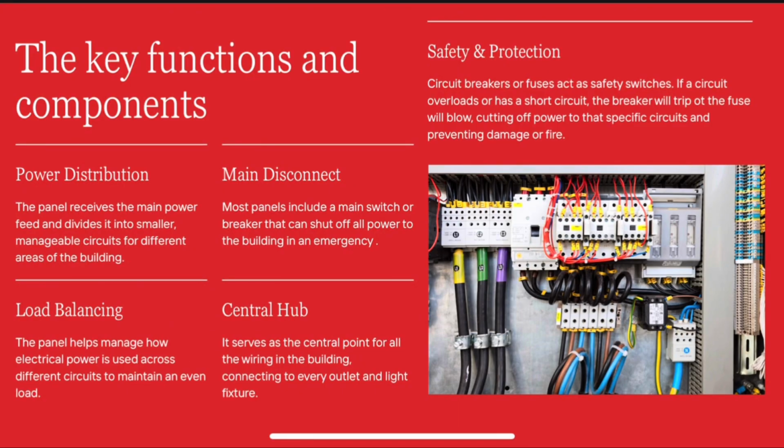Lastly, there is safety and protection. A circuit breaker or fuses act as safety switches. If a circuit overloads or has a short circuit, the breaker will trip or the fuse will blow, cutting off power to that specific circuit and preventing damage or fire.